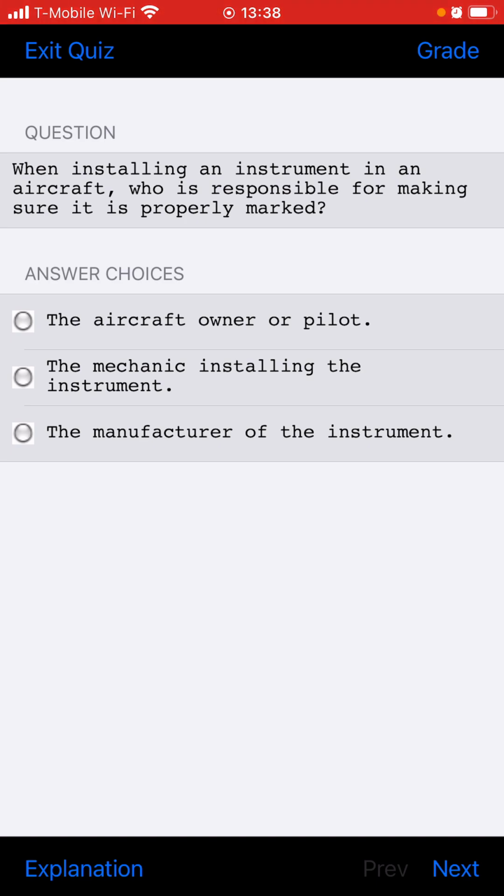Why do turbine engine aircraft have a fuel temperature indicating system? To allow the crew to determine if the fuel is cold enough to produce a danger of the formation of ice crystals.